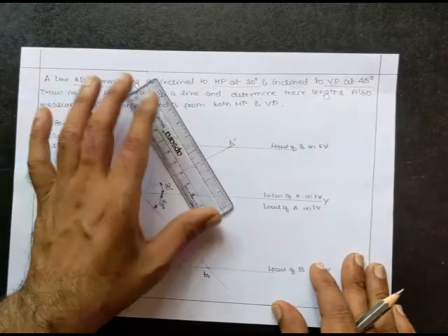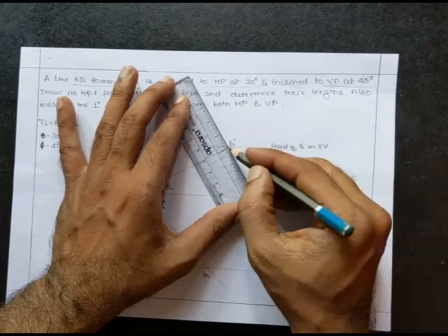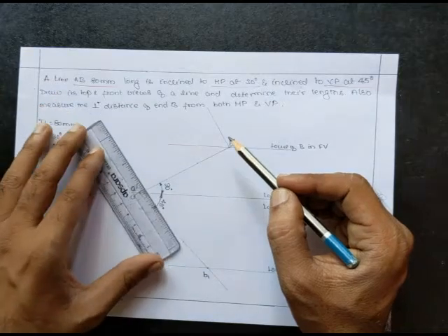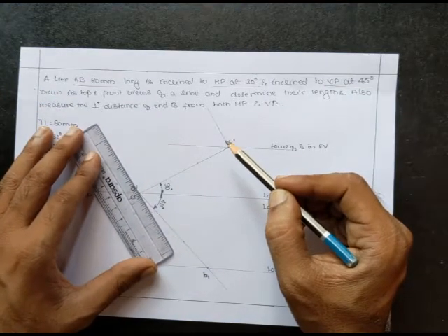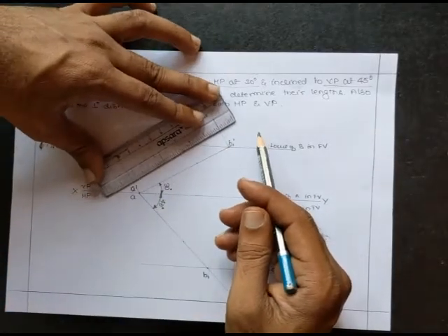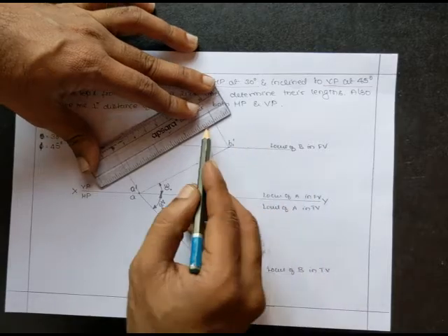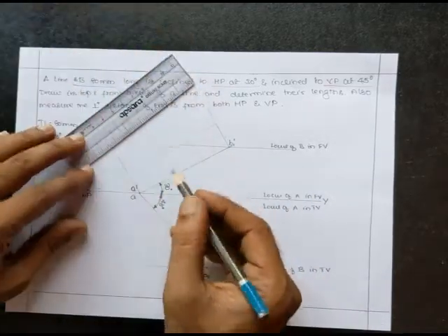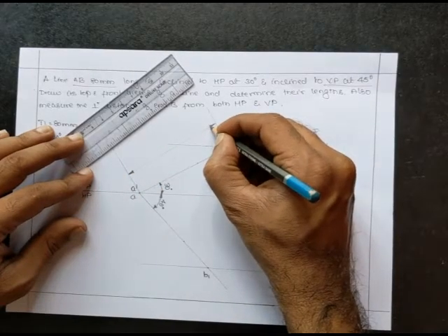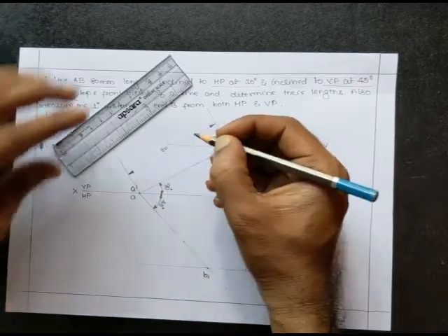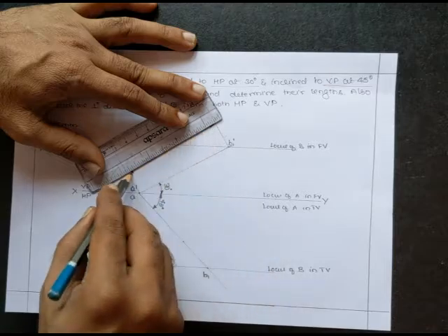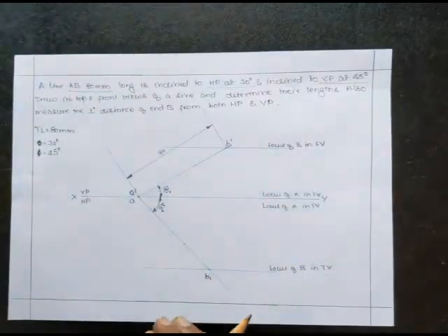So once you have done that, the next thing is I need to measure the true length on only one of the sides. So let me measure it on the front view itself. Let me do the dimension there itself. So try to always use the markings on the inclined side so that you can get parallel lines to the true length. It's better always. So let me draw somewhere else here so that the view length will not get disturbed. So slightly you can make it darker if you want. Right, so that's about the true length.